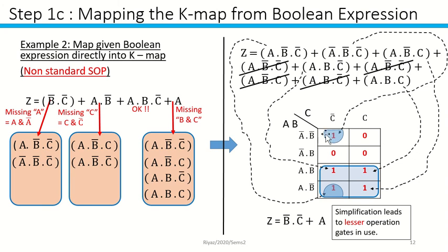Then you need to map it, group it into one. So for example, the biggest group you can form here is 1 2 3 4. So you have 4, you have to group over here. And don't forget, you have one over here, you have one over here, so this is adjoint, so you need to take this into consideration, and then you simplify, you get this one.